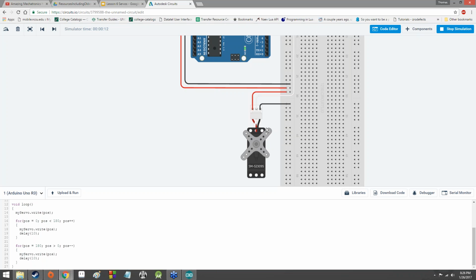If we did 1, the servo would be turning ridiculously fast. So we put the delay in there so that it actually spins at a sane speed. Servos are not necessarily terribly fast things, and so we don't necessarily want to have it spin that quickly. So we introduce the delay so it doesn't start flopping around like a fish out of water, and we don't potentially burn out the motor, because depending upon the servo, that is a thing that you could accidentally do.